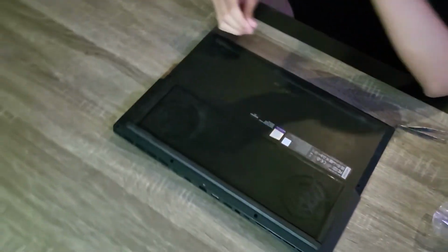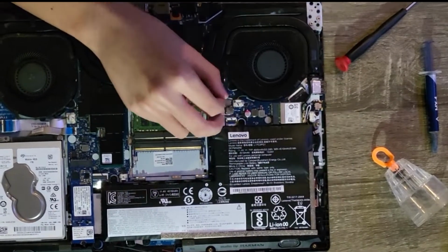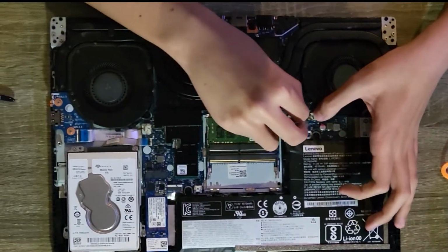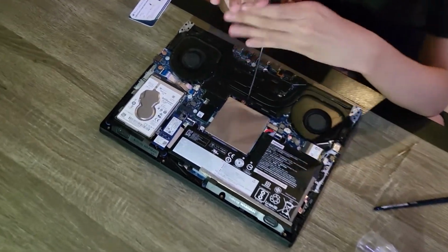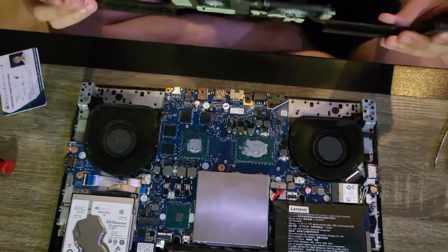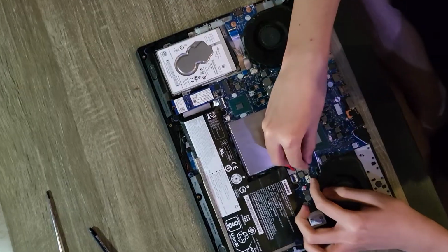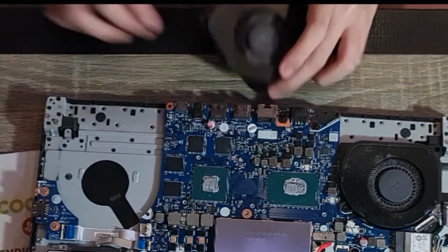Second, remove all of the screws in the back panel of the laptop and open the panel. Third, unplug the laptop battery to cut electricity from the motherboard for safety reasons. Fourth, slowly unscrew the heatsink. Make sure to put the screws properly in the screw container and slowly lift the heatsink. Fifth, detach the fan cable from the motherboard carefully and slowly extract it out.